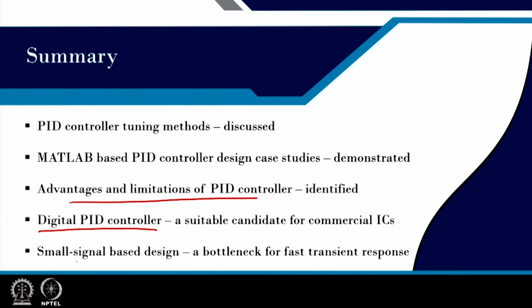The small signal based design has a bottleneck for faster transient response. In a subsequent lecture we will see large signal based PID controller tuning, because we are still talking about bandwidth up to 1/10 of the switching frequency or even less, but we can go up to the critical limit by setting the PID controller using nonlinear tuning, which we will also discuss. So with this I want to finish here.